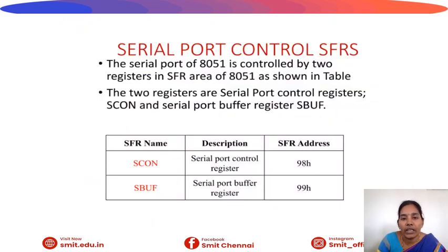In the serial port there are 2 registers, SCON and S-buffer registers. The SCON register address is 98H and the S-buffer register address is 99H. SCON is the full form of serial port control register and S-buff is the serial port buffer register.